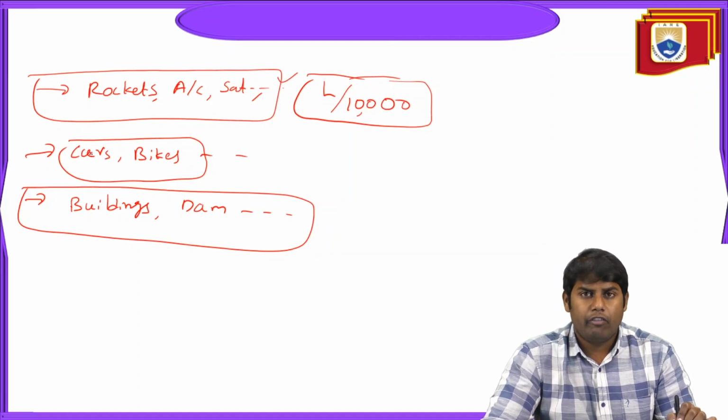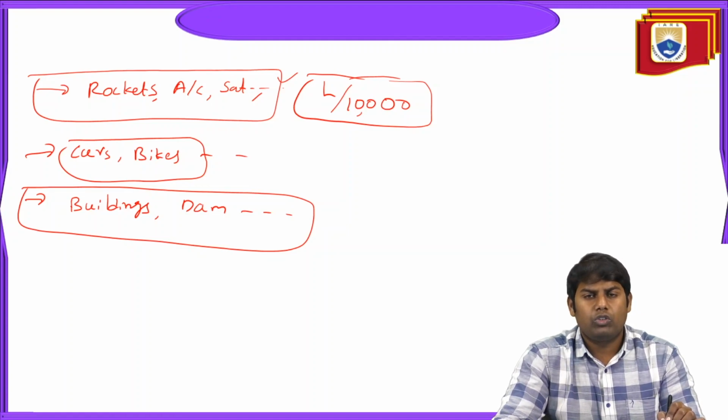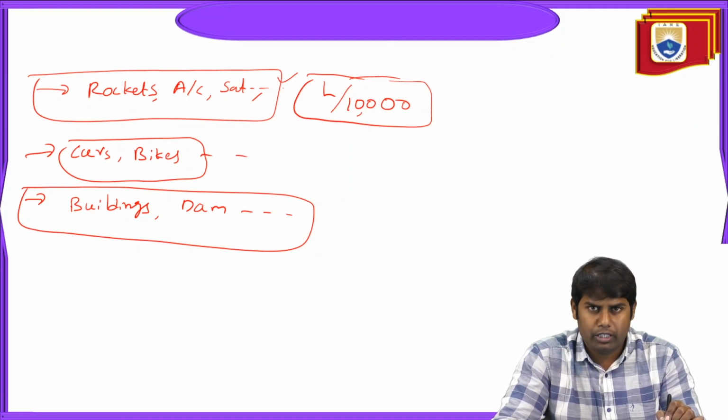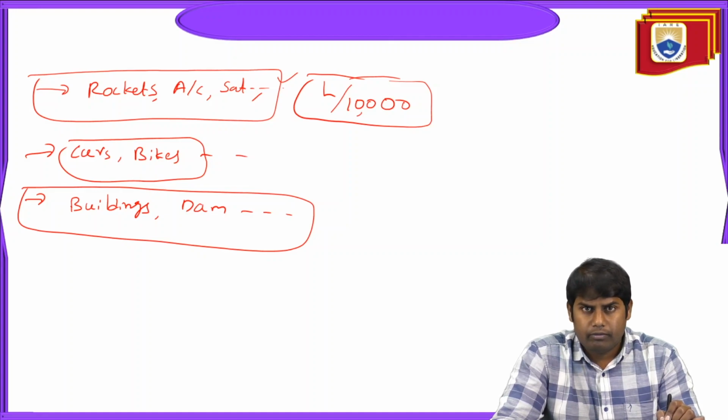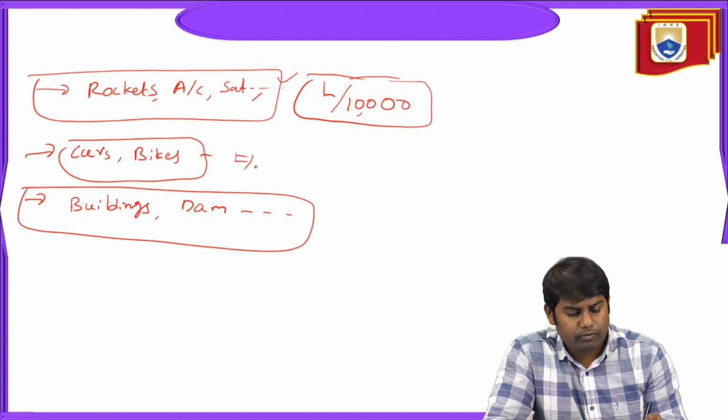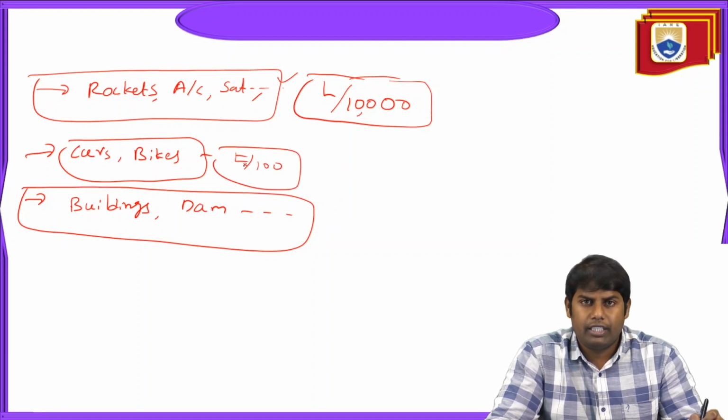Similarly, cars and bikes. Companies like Volkswagen, Audi, BMW may initially perform the numerical simulation, and they will have a toy model at, let's say, 1 to 100 scale. Those models they keep in the test section of the wind tunnel and then compare. They will have test sections with the length and width of the car, where they want to check the actual properties of the flow over the cars. For racing cars, they will see whether they are able to minimize the drag, and whether they are able to minimize the flow separation or not. These things they can do.